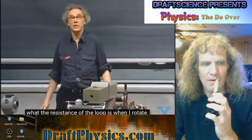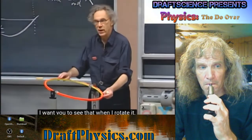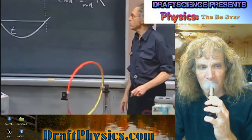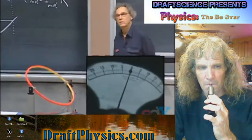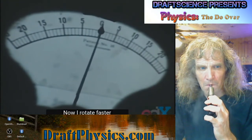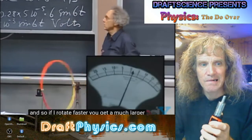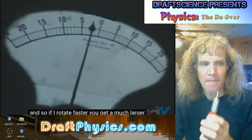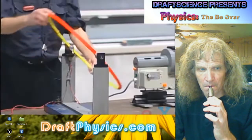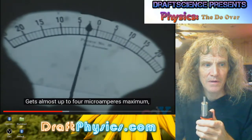Calculate what the resistance of the loop is when I rotate, but that's really not my objective. I want you to see that when I rotate it, you get an alternating current. Very modest, because I rotate very slowly. Now I rotate faster, and it's proportional to omega. And so if I rotate faster, you get a much larger maximum induced current. A larger EMF, a larger current. I don't know how fast I can go. This is about as fast as I can go. It's almost up to 4 microamperes max.